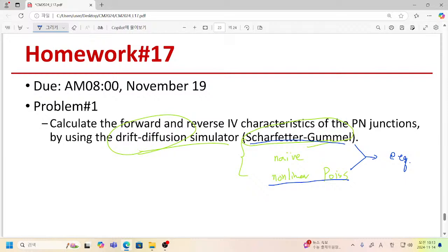If your residue gives an unreasonably large value when evaluated with the solution of the nonlinear Poisson equation, it means that your Jacobian or your residue function is completely wrong. So please try to fix your problem.